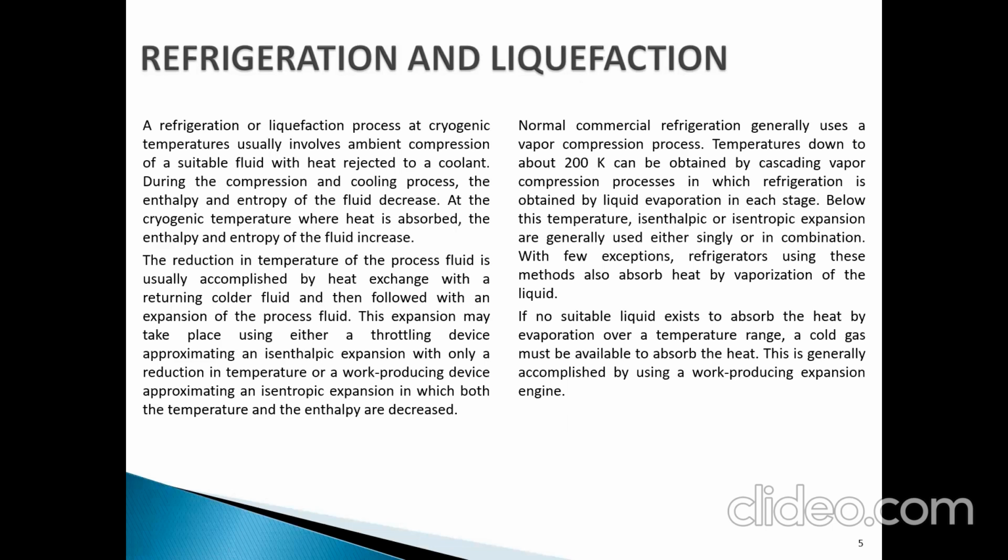This expansion may take place using either a throttling device approximating an isenthalpic expansion with only a reduction in temperature, or a work-producing device approximating an isentropic expansion in which both the temperature and enthalpy are decreased.